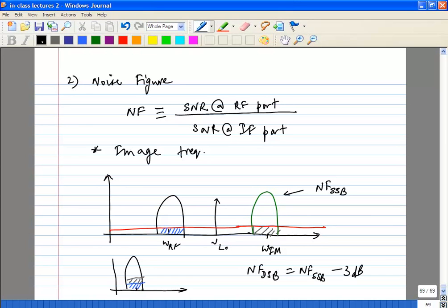So it is equivalent of considering only one noise level. If I have only RF and its own noise floor, that is exactly the same as considering two sidebands. Exactly, that is right. In a measurement, you can't constrain the noise at the image frequency. Whatever you do as far as filtering goes, the noise floor will still be there. There will still be some broadband noise coming in. You can get rid of the signal but not the noise, because the noise floor is typically very much lower.